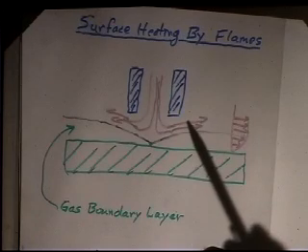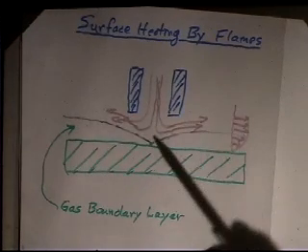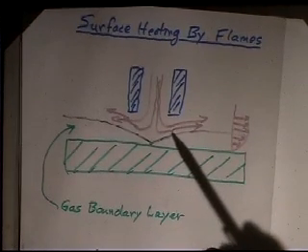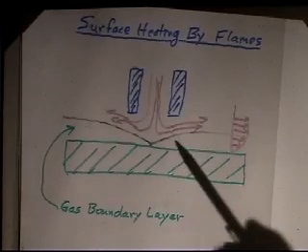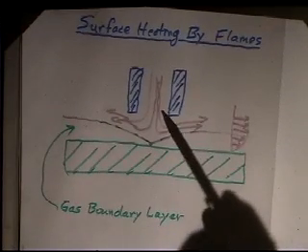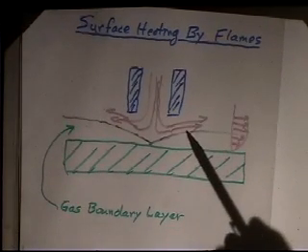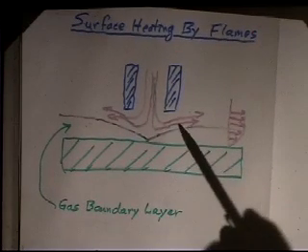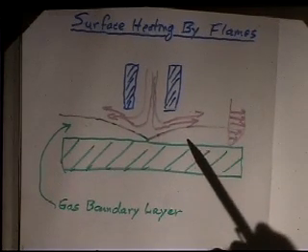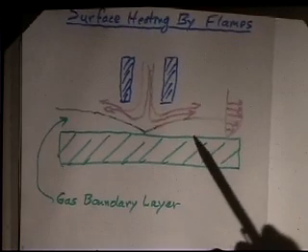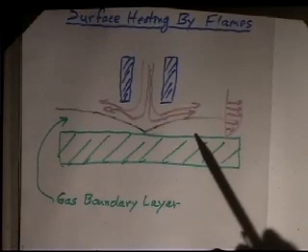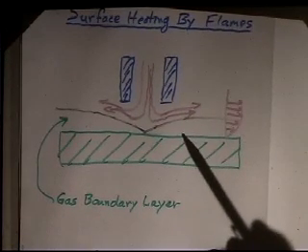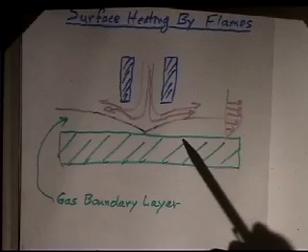So everybody knows what a boundary layer is? Boundary layers are the way that you can fly. You know, birds fly. The Wright brothers figured it out. So it turns out there is a thermal boundary layer. When you have this velocity boundary layer, there's a thermal boundary layer here, and the heat has to diffuse across this stagnant layer of gas. And that's what changes your efficiency from 100% heat transfer efficiency to only 2 to 10% efficient.